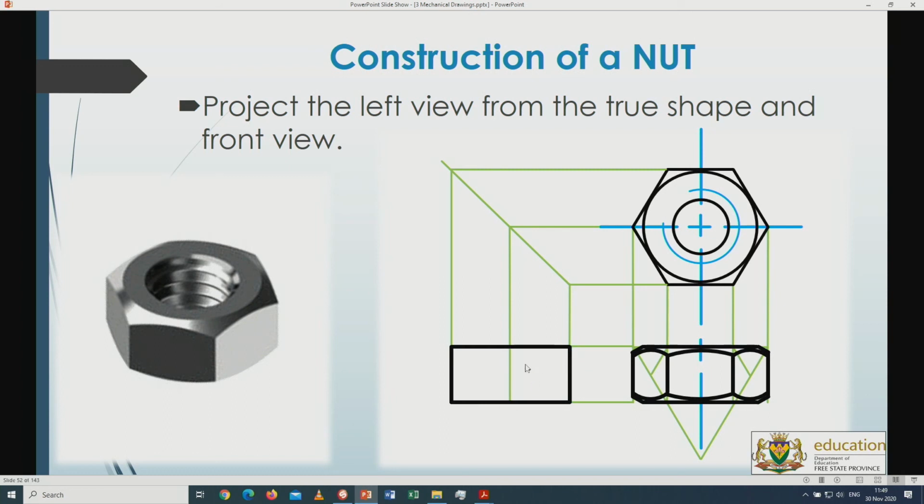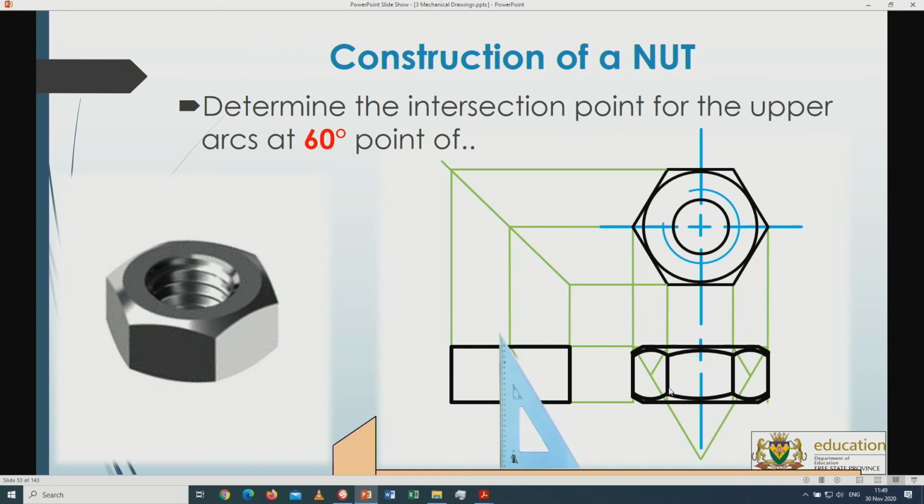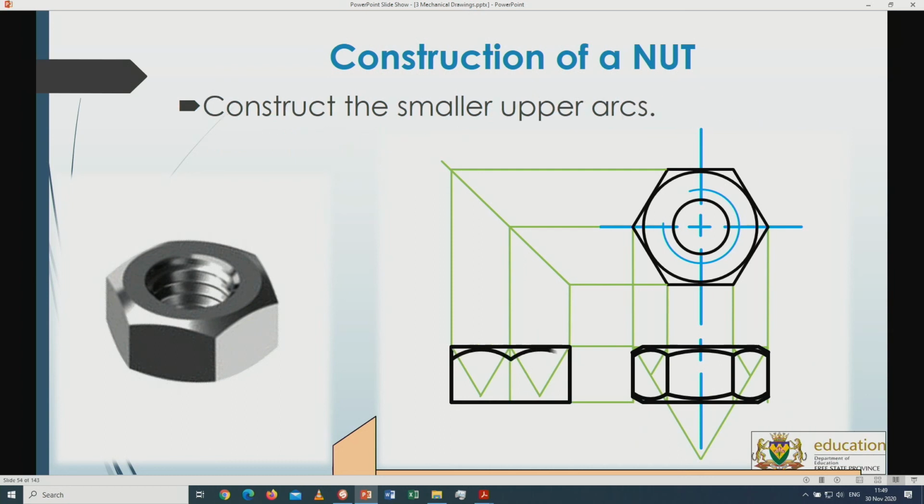How do I get the arc or the size of the arc? Because I'm going to have two sides with arcs over here. Same principle as what was applied for this part over here, is to draw those 60-degree ends in there, and then from there on use that intersection point for the size of the circle or size of the arc up to the tangent line.